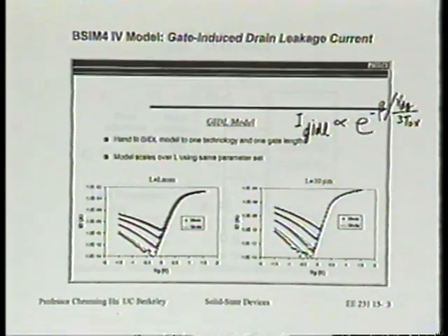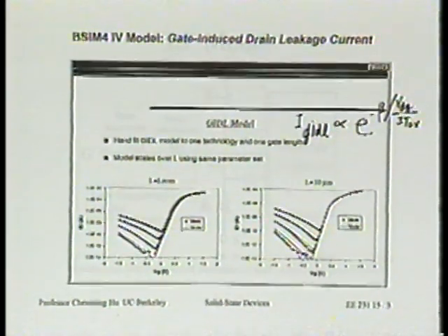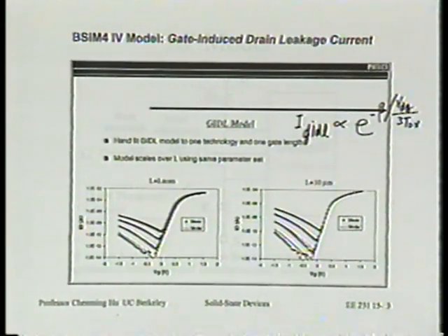Now, physically, that's not possible, because if we don't have voltage between the body and drain, then the junction will not be in deep depletion. The reason it's in deep depletion is because of the body bias. If not in deep depletion, there will not be band-to-band tunneling.